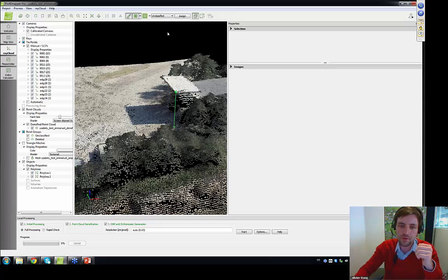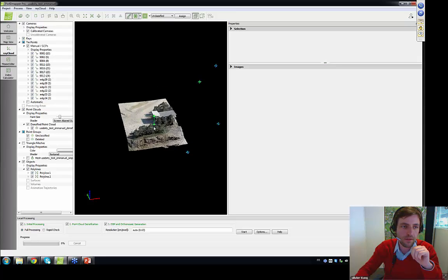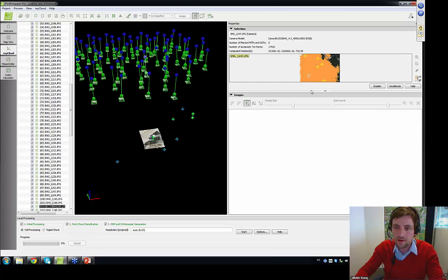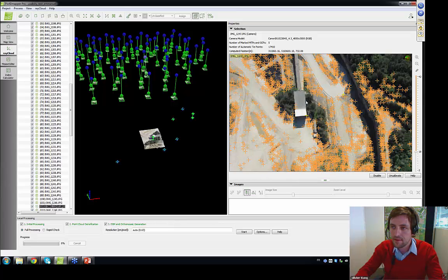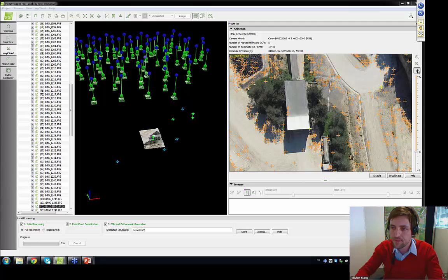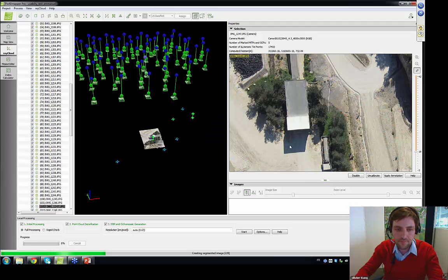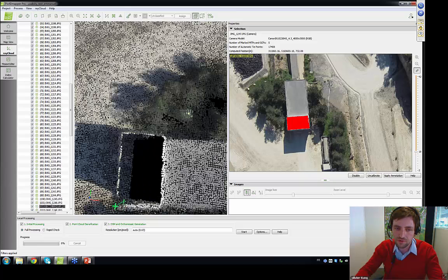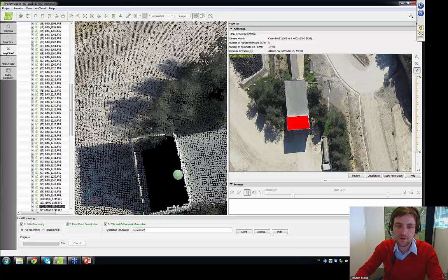And then finally, if you have more foreground project or very oblique project, if you have sky in your project, another way to do it is to click on a camera. Let's, for example, click on this camera, and there on the side, you have this little pen tool. If you click on it, you wait a little bit, and then you are able to draw on top of the image. I just selected the whole thing there, and I click Apply Annotation. If I say yes there, you will see that my whole roof just disappeared. The roof I just selected with my annotation tool. So that's another way to delete points quickly.